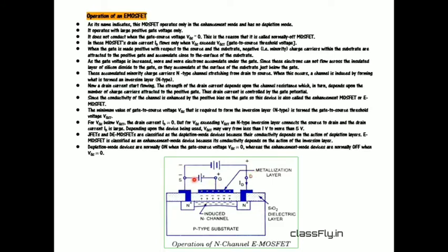But when we supply the gate, at this point of time a positive charge occurs here. So here also we will have some positive charge, and due to that it will attract the negative charge, and what happens is it will create an inversion layer as we increase the positive charge on this gate.